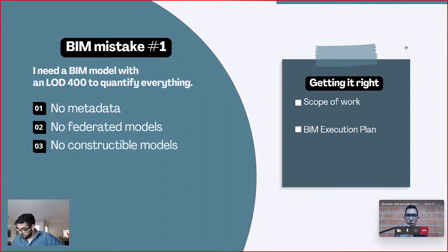Right on. And just to wrap this up, I want to mention that when you tackle the BIM models to an LOD of 400 overall, modeling everything to the highest level of detail possible, you end up creating unmanageable files. I made this mistake in the past and it was crazy. You cannot manage any model with an LOD 400 because it becomes really heavy in file size, unmanageable, because you're adding more information than needed. It's kind of a beginner's mistake, but hopefully with this information, people will know how to avoid it.